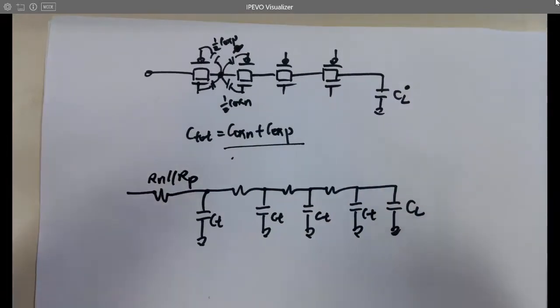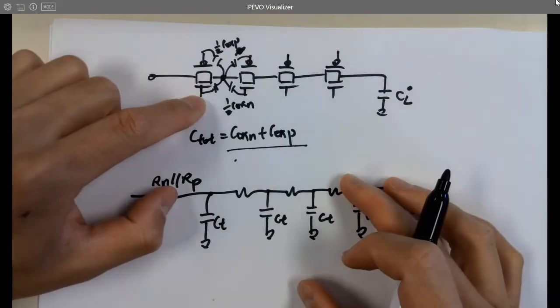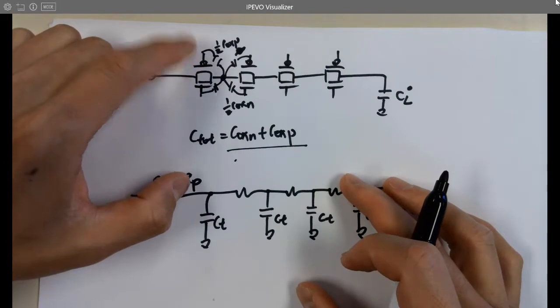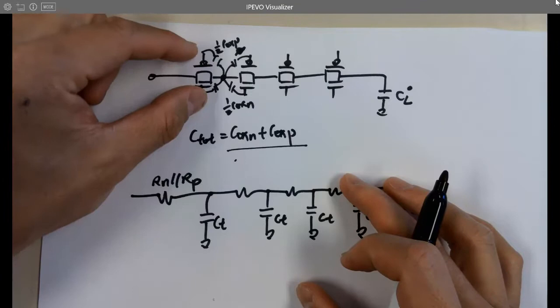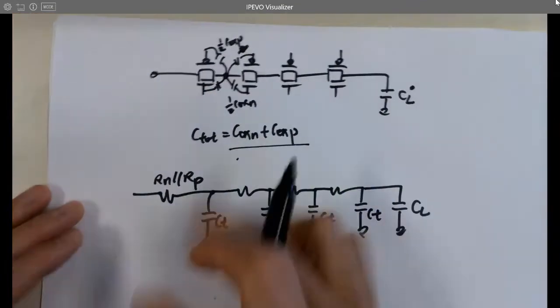You want them to be both on because PMOS is good at passing VDD and NMOS is good at passing 0, right? Whenever the transmission gates are on, you want both of the NMOS and PMOS on, so you can pass the signal through. You're not turning one on, turning one off, right? That's why the clock for NMOS is always inverted, and then you use the inverted clock for the PMOS. They're both on when you are operating that transmission gate. So that's how you can model it.